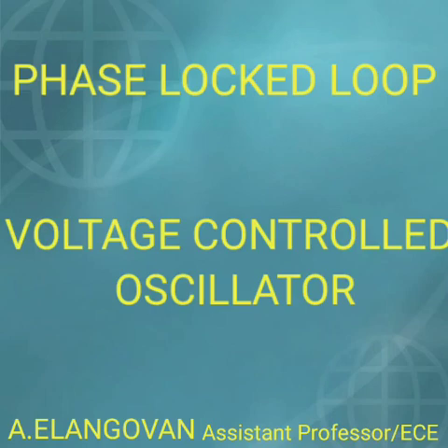Hello, welcome to everyone. Today we are going to discuss the topic phase lock loop, PLL, which is an important topic in communication engineering. The phase lock loop is an electronic circuit with a voltage controlled oscillator that constantly adjusts to the frequency of an input signal. PLLs are used to generate, stabilize, modulate, demodulate, filter, or recover a signal from a noisy communications channel.